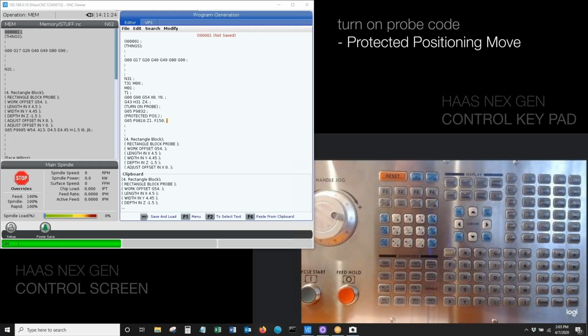So for those out there who are like, whoa, 150 is kind of fast, right? Actually, when we're in 9810, as long as we're under 200 inches per minute and the stylus hits something that shouldn't be there, it will actually stop the machine fast enough to where the stylus will not break. So anything that's 200 or below is perfectly fine for a 9810 move.